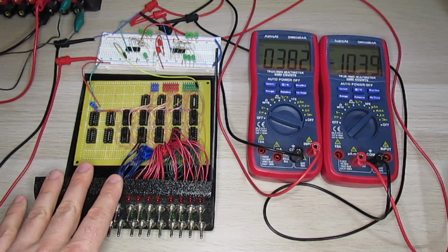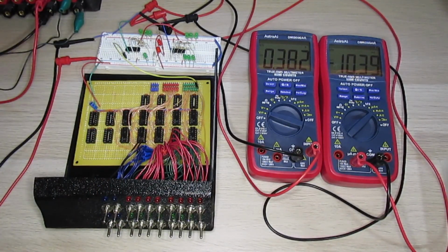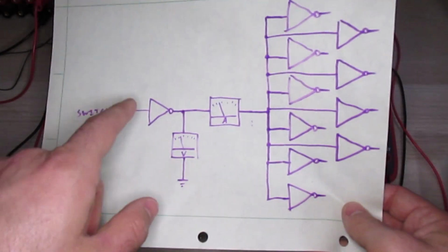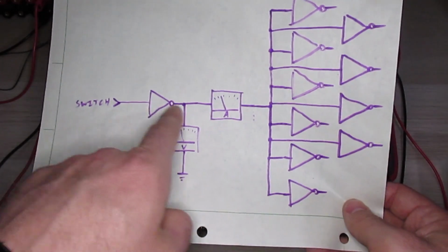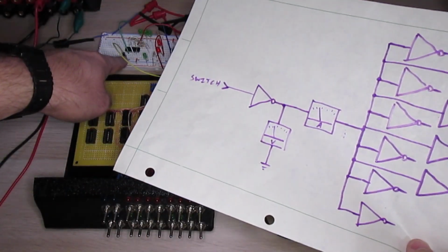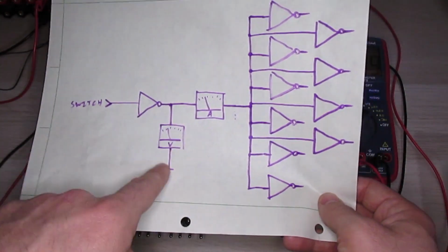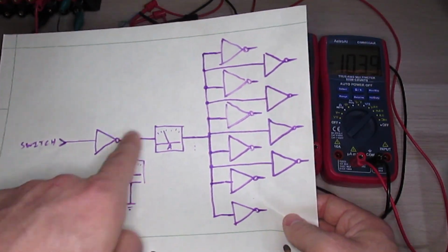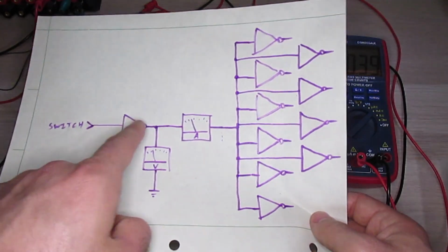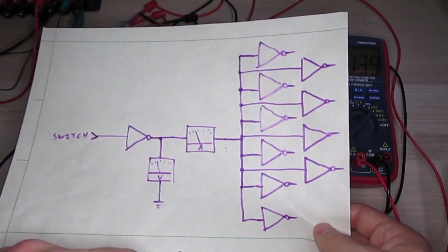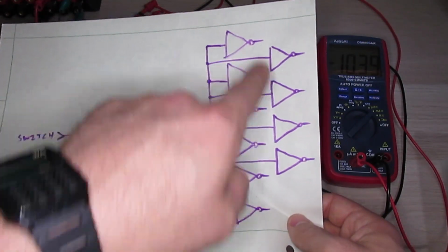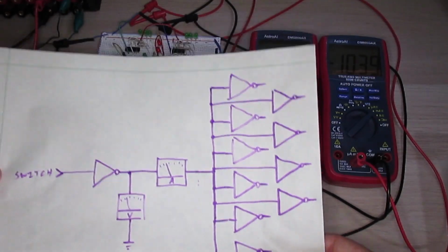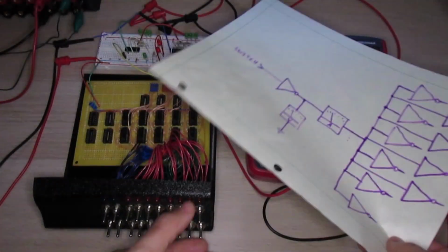So here's the test circuit I put together. It's going to be hard to see what's going on there, so I made a schematic. I also have a switch from my switch box that is connected to one of the inverters on one of these 7404 chips, and the output of that has a voltmeter, which we can see the output voltage, and an ammeter in series, that's this one here, so we can see how much current is going in and out of that output. And then it's connected to a whole 10 more inverter inputs, which is the maximum fan out that we came up with earlier, and that's what all of these little green LEDs are on.